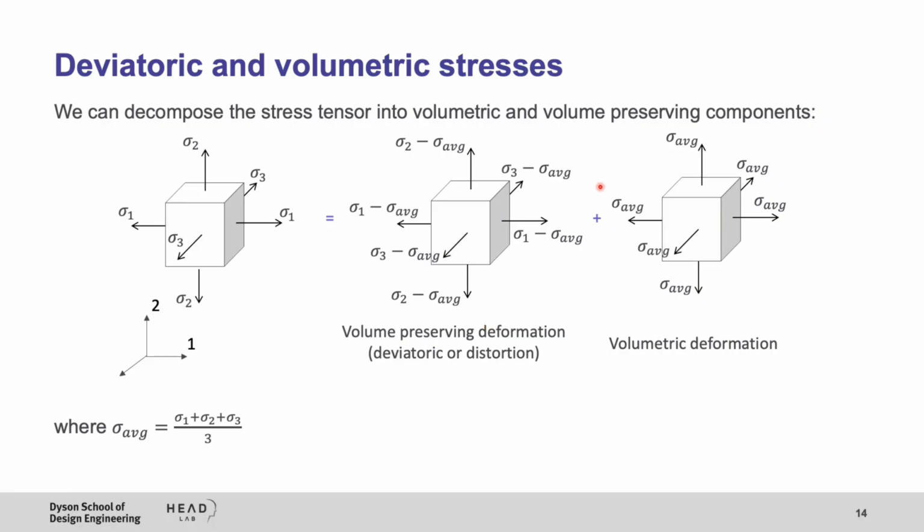And this set of stresses can only change the volume of the element. They cannot distort the shape of the element. An example of this stress state is hydrostatic pressure, like placing a metal cube down in the ocean. In fact, it is shown that if you put a metal cube down in the ocean, it will not fail no matter what the hydrostatic pressure is.